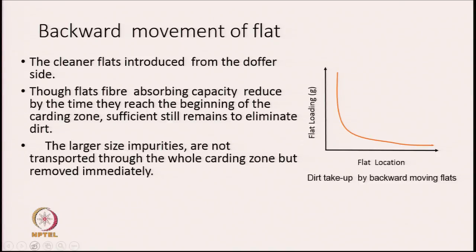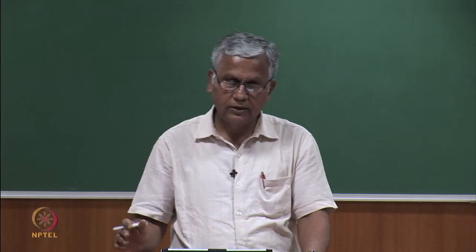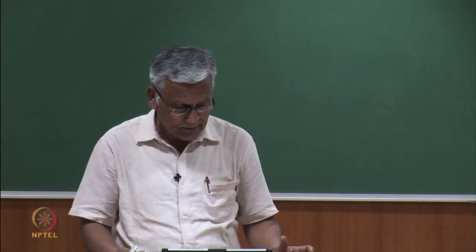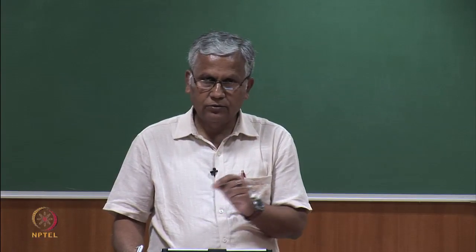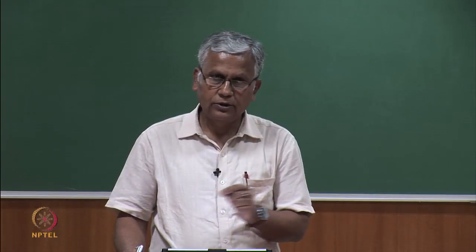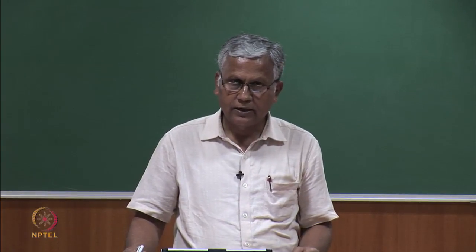From the carding point of view, there will not be any problem, carding action will still be there. Now, this time the cleaner flats will be introduced from the doffer side. So, from the front of the machine, the flats will be introduced and they will move backward. Though the flat's fiber absorbing capacity reduces by the time they reach the beginning of the carding zone, sufficient still remains to eliminate the dirt. That is, when the flat reaches from the front end to the back end of the machine, where the carding zone starts,